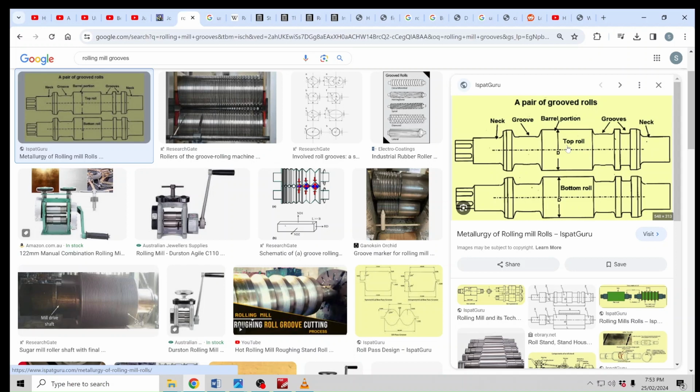So something to understand is that this has a bit of a limitation. The size of the grooves of that particular roller are fixed to the size of steel. So basically one roller for one size. It was a slow process because if you wanted to use a material to roll out a different size beam or whatever shape, you'd have to change over the rollers. So this is a bit of a limitation with this type of setup.